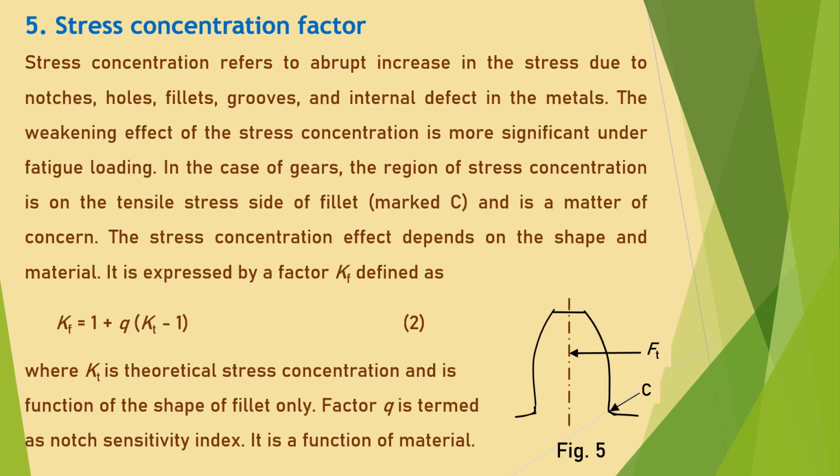The stress concentration refers to abrupt increase in the stress due to notches, holes, fillets, grooves, and internal defects in the metals. The weakening effect of the stress concentration is more significant under fatigue loading. In the case of gears, the region of stress concentration is on the tensile stress side of the fillet, marked as C in the figure, and it is a matter of concern.